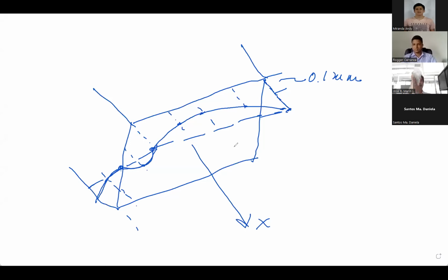Now, what we are seeing is that because of the shear, it does this, but also it makes something like this. Well, this is extreme. So it's not straight anymore. Okay, and because of this, in the closed section, it does something similar in between. This elongation generates a change in the normal stress distribution. That's what we are calculating. So that's why I prefer, Ms. Santos, that you try to summarize this in a 3D diagram.